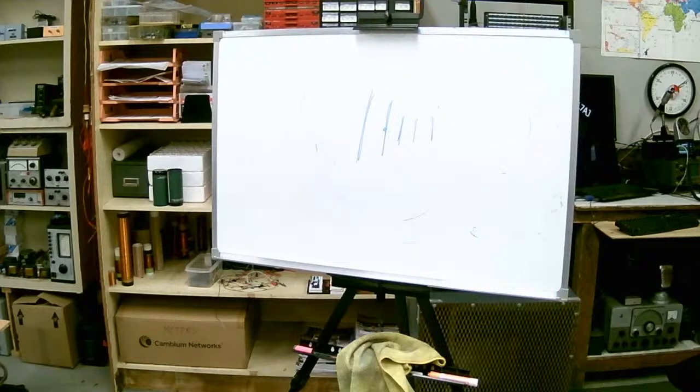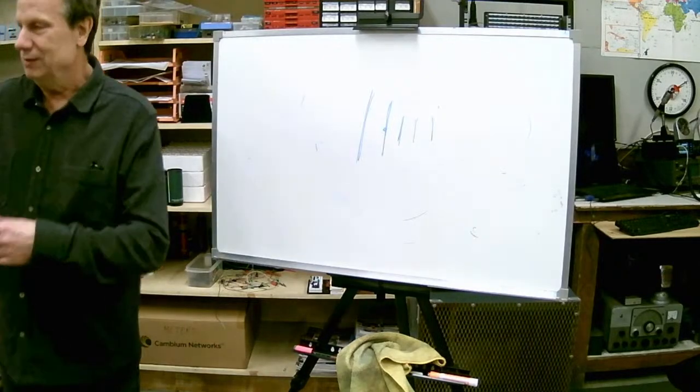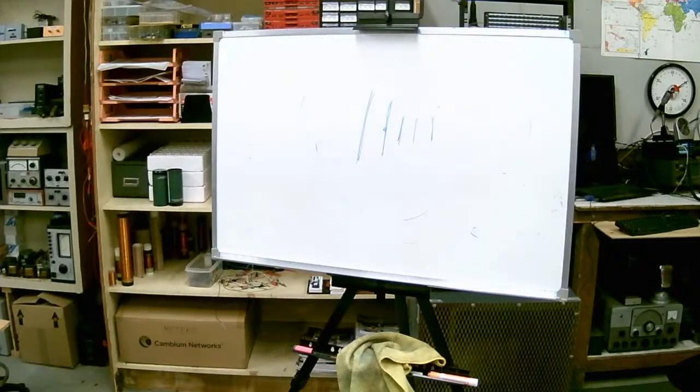This was a hybrid log periodic. It's a receiver, or actually a transmitter. Well, it's reciprocity, it wouldn't matter. It works out for either one. Most of your TV antennas are designed to run over a very wide frequency range. A Yagi is only like that 900 megahertz. That'll only work at that frequency.